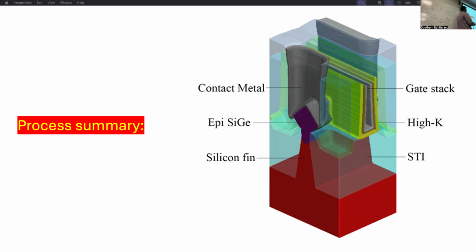So this is the final structure. And after this, the job is not done, right? Because you have an inverter, so you still have to connect the transistors together. So then you do the back end of line. Back end of line is not that difficult. You put oxide, create a pattern, then put a seed layer, electroplate copper, CMP, and then you create metal 1, then dual damascene to create metal 2. That completes your thing. So on top of the front end and middle end, you'll have 2 levels of copper that define your back end of line, and then you have the fully interconnected transistors.